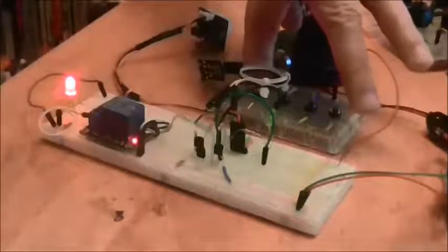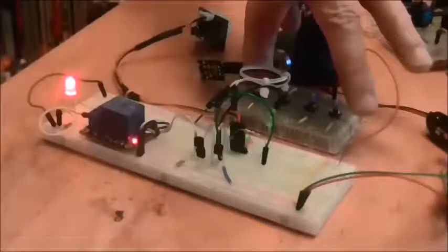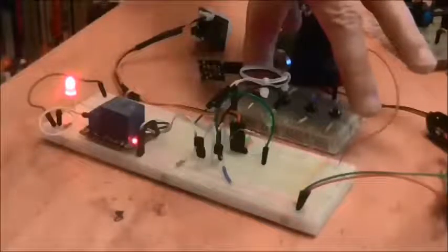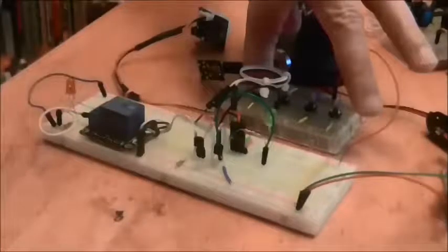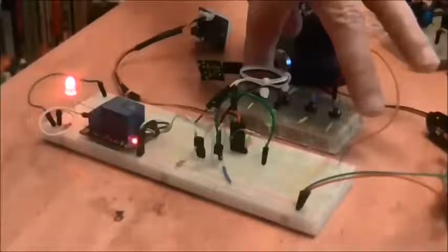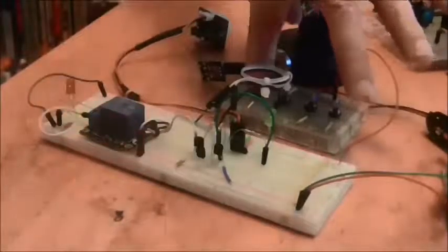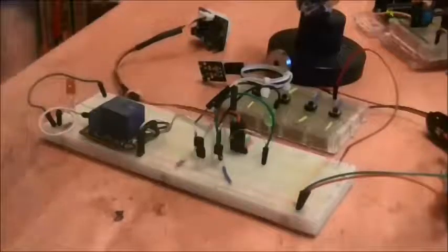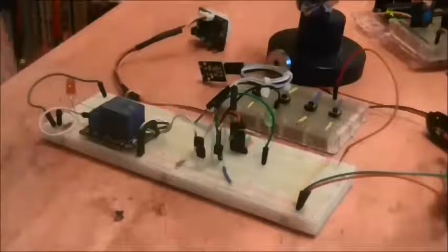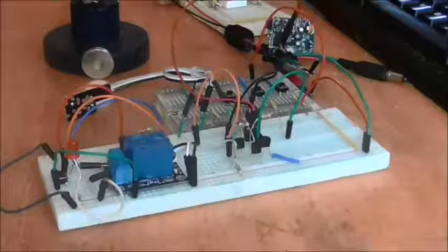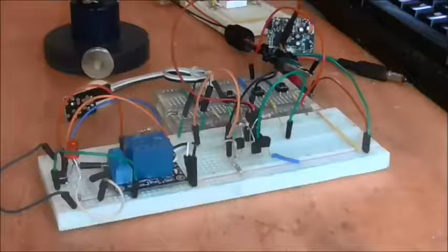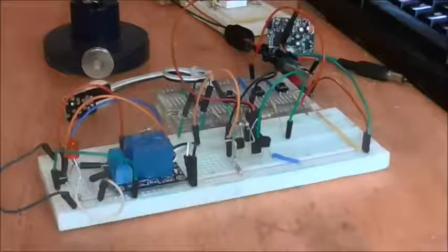To be an effective alarm system, this really needs to latch that relay, and there are 2 ways we can do that. We can do it mechanically and electrically with the relay, or we can put a thyristor in. And the easiest way is of course to put a thyristor in there. Now, despite what you might just have heard me say, putting a thyristor in here was not the easy option. In fact, it turned out to be a very horrible idea indeed.